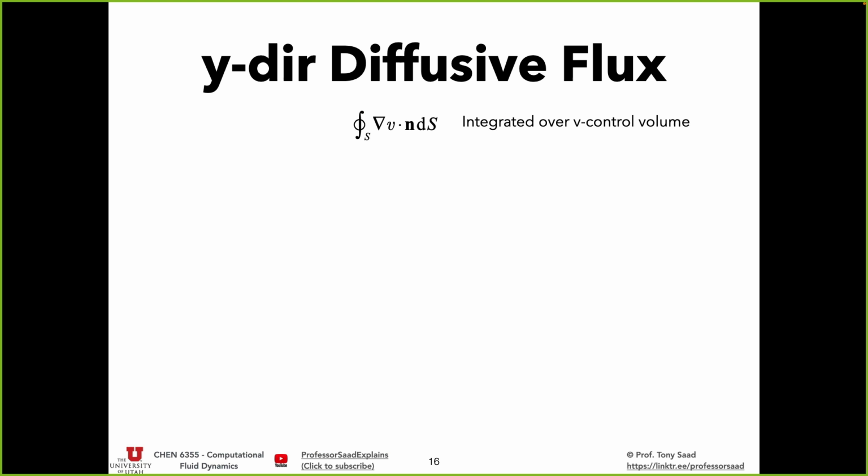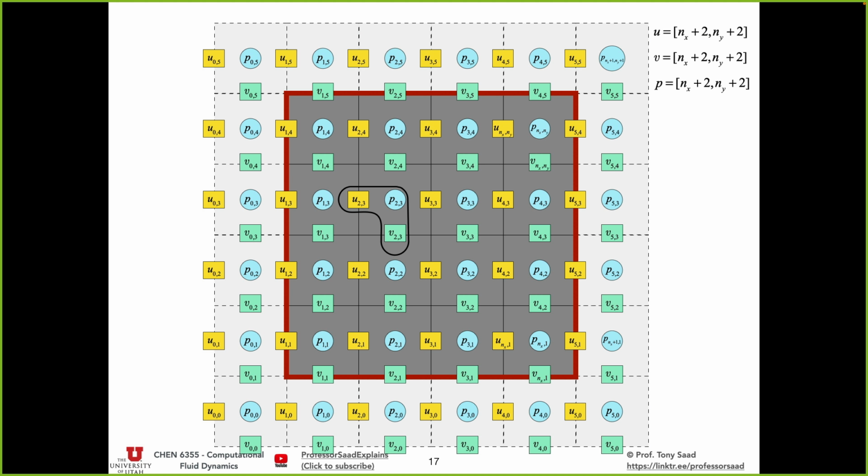So in other words, if you were to go to this grid, you would say, okay, I have a wall over here, U and V are 0. I can directly set these values to 0 because they're all U. But I don't have a variable V over here. I only have v here and v here. This is part of the solution process. I'm going to use the old values to set a value here that on average produces a 0 v. So I set a value here, and then I run my time advance. When I hit this v control volume, I'm going to use fluxes between, doing averages and whatever. Well, guess what? I have a value already here that will produce a net zero velocity here, which is good.